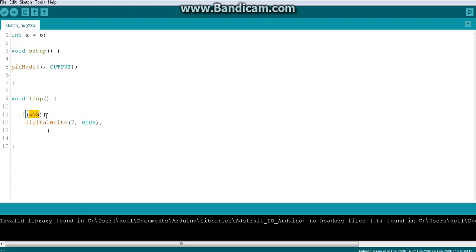Get it? So if we have this greater than operator, that will be the way it works. What we will do is take that analog read, analog input scenario, and read the analog value, maybe using a preset, the variable resistor that I have taught you, because when you rotate it, the value will change. Then, if the analog value is more than a particular value, let's say more than 511, we will switch on an LED.